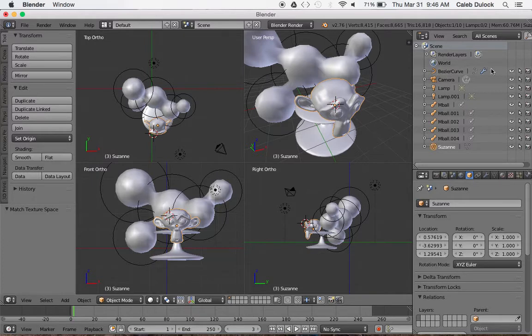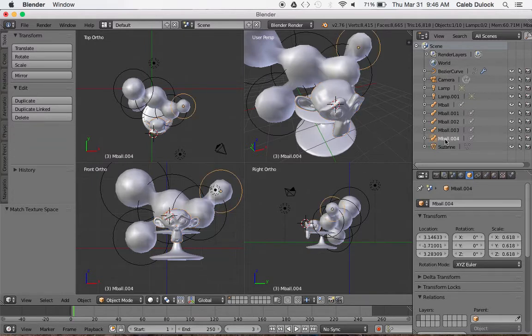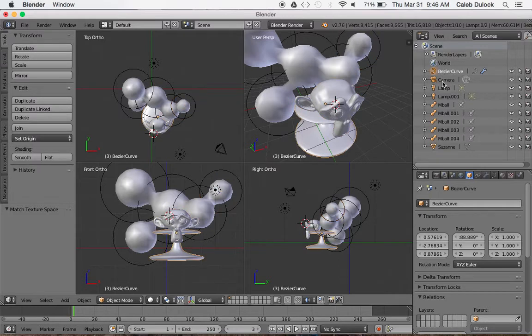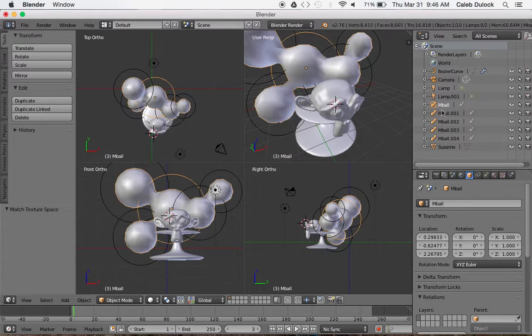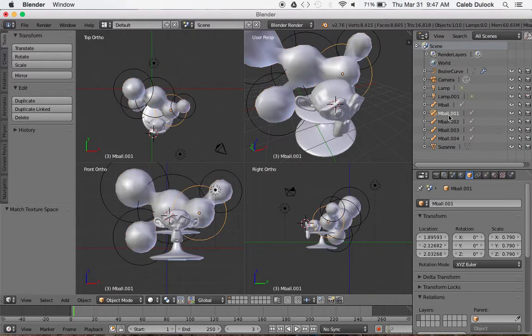So we very carefully look up and down the list, make sure there's no objects that we aren't using. You can very quickly select and click down through the list to make sure as you select them that they are visibly present inside the model. If you select an item and it does not appear inside your scene, then that may be a good time to get rid of that particular item.